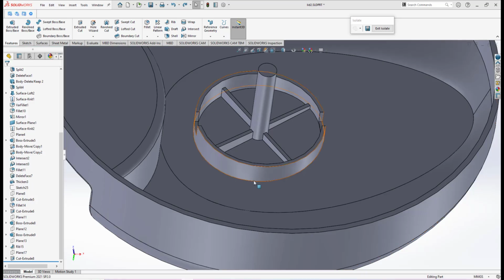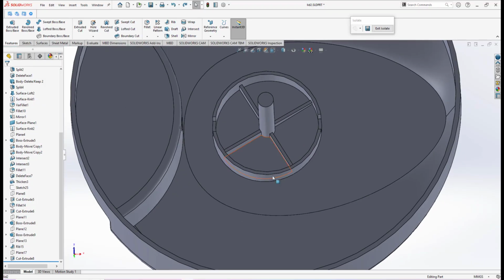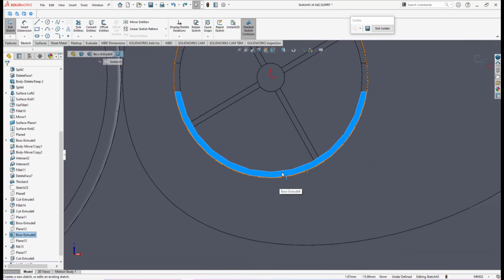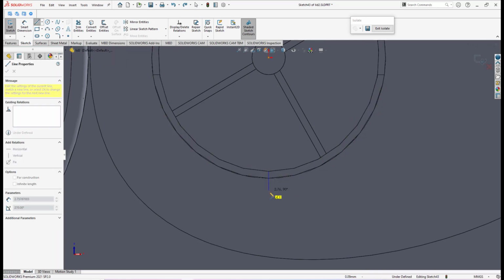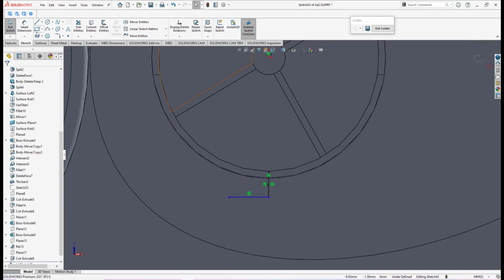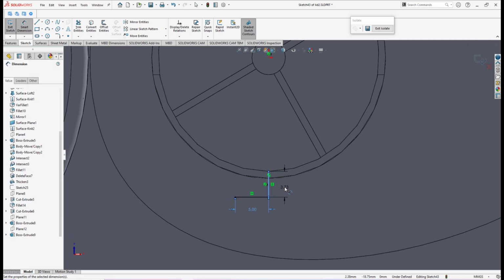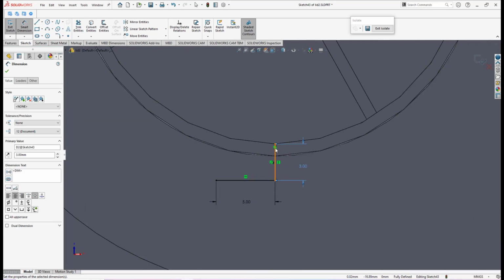Okay, in Solidworks, since my view is on the other side, I will do the cutting slot at this plane. At this plane, I will create a sketch. I will create a line from this quadrant up until here, then create something like this. I give the dimension here as 5 units, and the dimension here is 3. So we have an L shape.